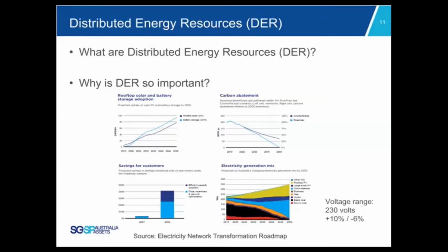However, our electricity network hasn't been tested for the dramatic increase in PV penetration to meet the requirement of the Australian standard distribution voltage limit between 216 to 253. As an electricity network provider, we definitely need to review our network before it gets worse.